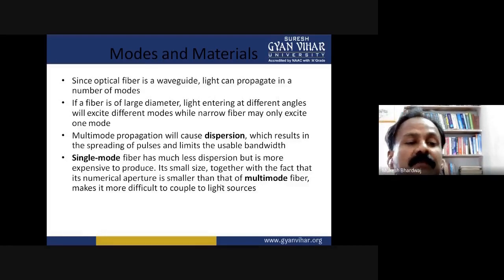Now single mode fiber. Single mode fibers can have either a step index or graded index profile. At present, commercially available single mode fibers are still usually step index. They are high quality fibers for wide band, long distance transmission, and are generally fabricated from doped silica in order to reduce attenuation.